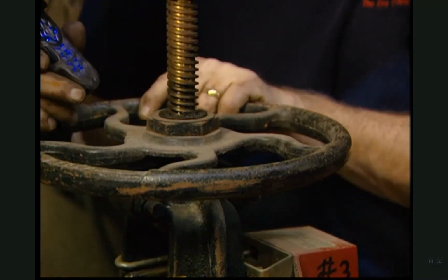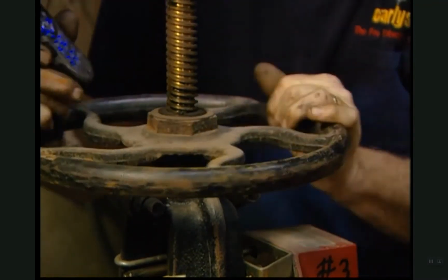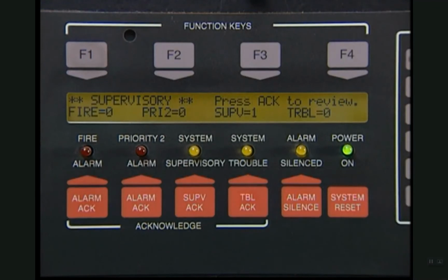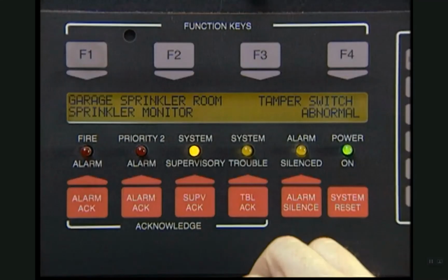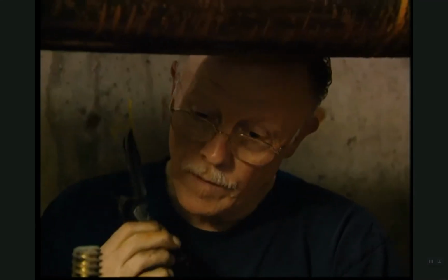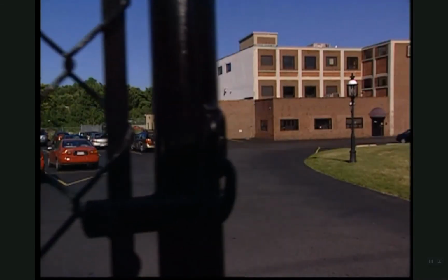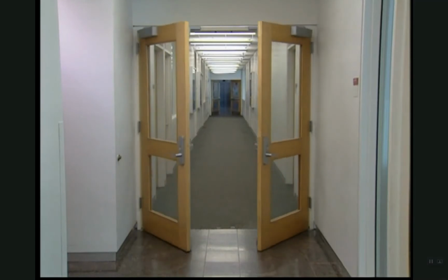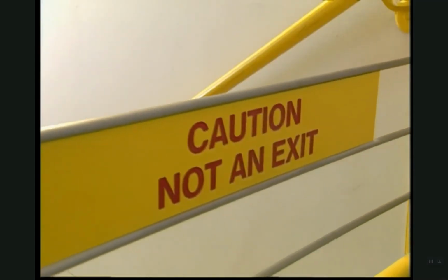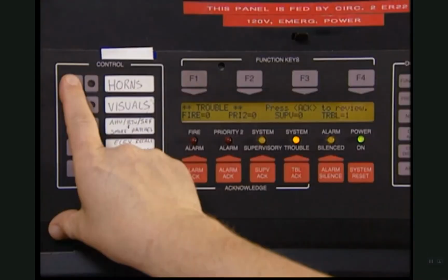Conduct functional tests on the control equipment to verify correct receipt and transmission of input and output signals, circuit supervision, and power supply supervision. Reset, advise when clear, please. Also apply functional tests to any interfaced equipment, following the manufacturer's recommendations for that specific equipment.